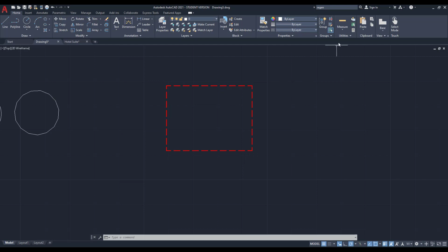For example, right now it is 1 3/4 of an inch, and for example, you want it to be 3 inches, right? You want this side to be 3 inches. And you don't know the scale factor for it, right? So you don't want to calculate that. You want AutoCAD to calculate that for you. So this time, actually, we are going to use the reference option for it.